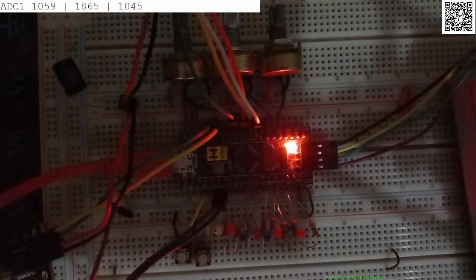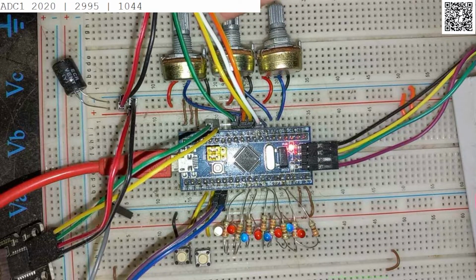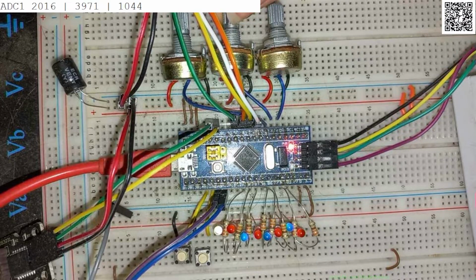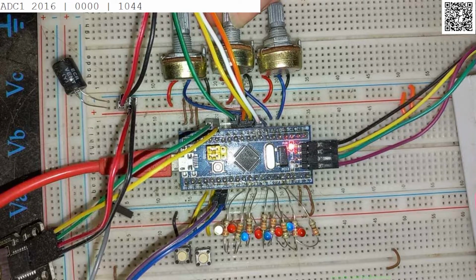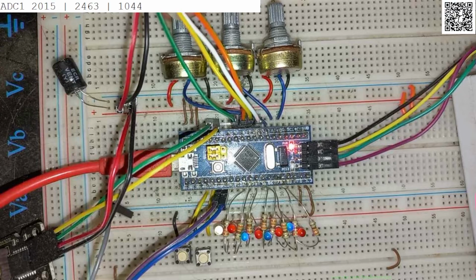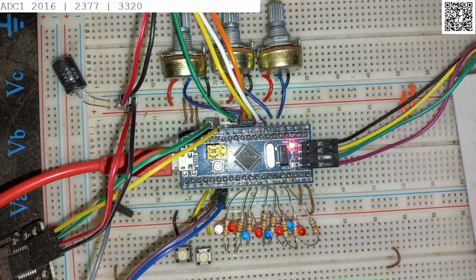So let's go to the camera. Now, as you can see on the top, I believe it's left. Let's see, if I adjust one of the outer pots, you'll see the first value go up and down. So this is your raw ADC reading. You can see it only goes to like 3,900 on this particular one. Then we have the middle one that's adjusted up and down, minimum 0, and then again 3,900. You can fix it with calibration if you really want to, but I'm not going to be covering that. The final one is being a pain.